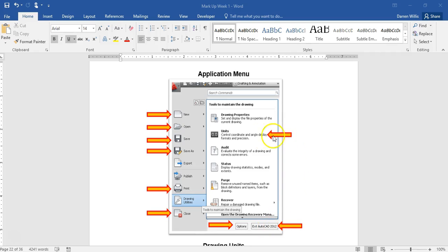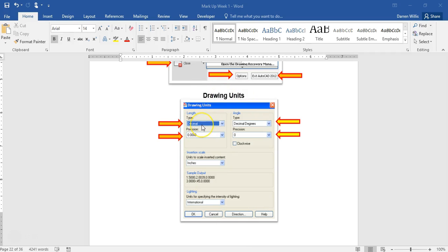We also have a tool here for going to set the units, and this was the options button, and we explored some of the display properties and options that we want to have control over. Under drawing units, of course, AutoCAD starts out as decimal units, rounding to the nearest 10,000th, or 4 places to the right of the 0. For length measurements, these are the two you already know. What I wanted to show you over here was the other settings. See, these are length settings as we measure and identify length. Here, though, we're talking about angles. How is AutoCAD going to measure angles?